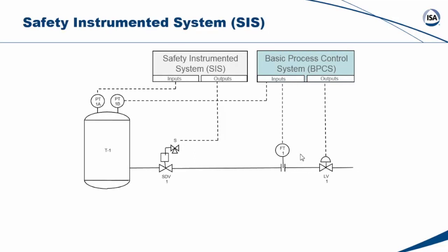What are they? What is that name? The common name for these in the past was ESD, not for electrostatic discharge, but for emergency shutdown system. And a lot of people didn't like the word emergency, it has a bad connotation. So it was somewhat softened up in the mid-90s to safety interlock system and then to safety instrumented system.